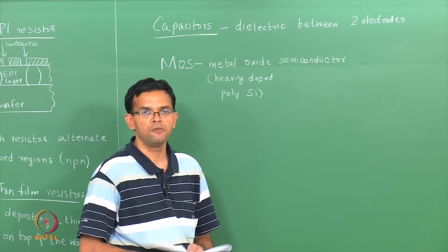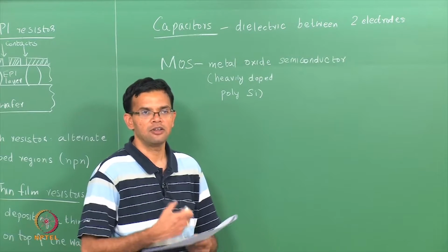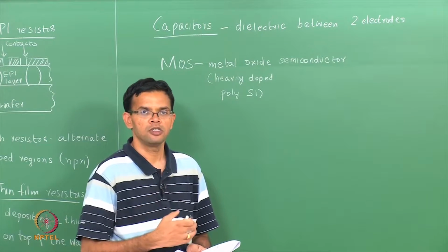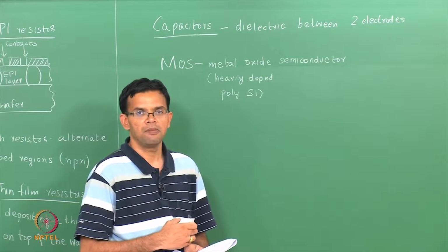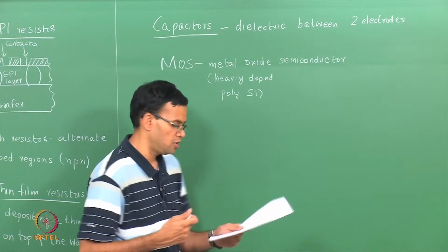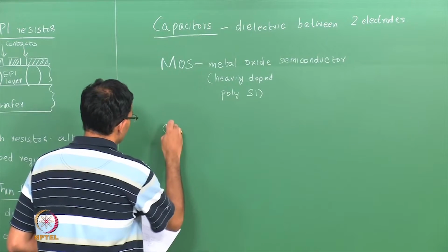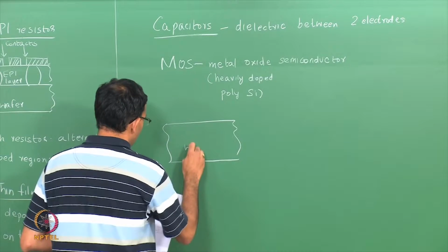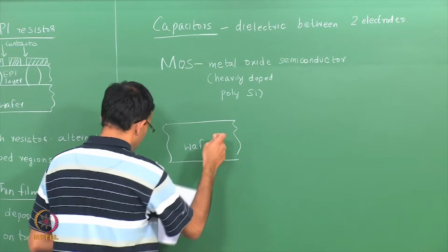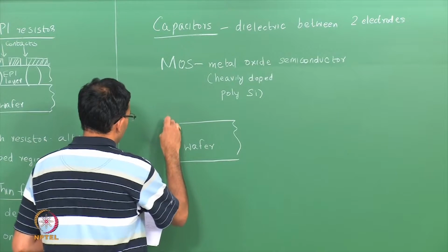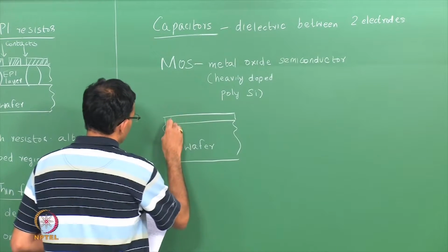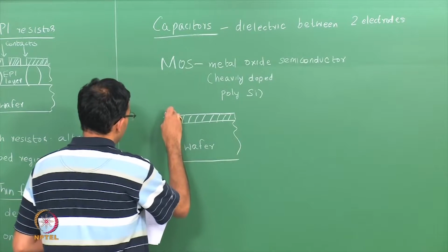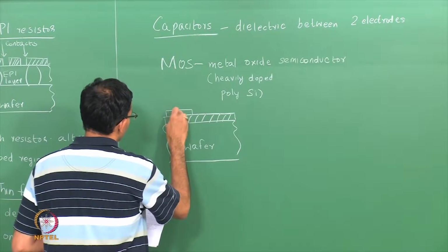So, similar to a doped semiconductor, you can once again grow an oxide layer and use lithography in order to open holes, so that you can deposit the metal and also the electrical connections. So, this is just a schematic showing the formation of a simple metal oxide semiconductor based capacitor. So, we grow the oxide layer, a metal is then deposited on top,